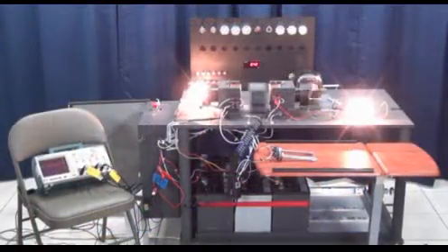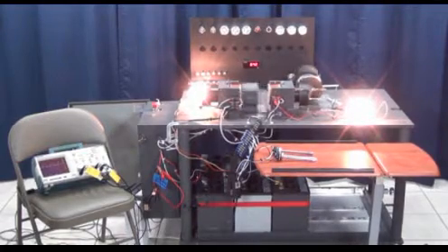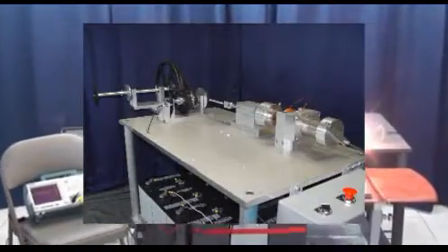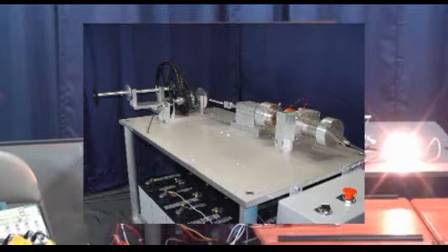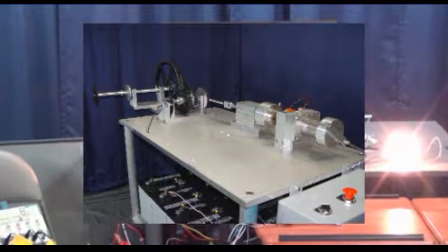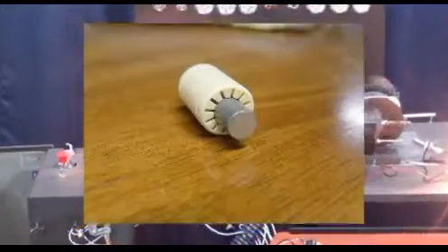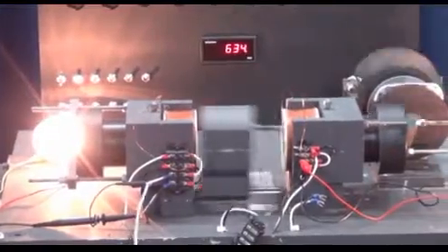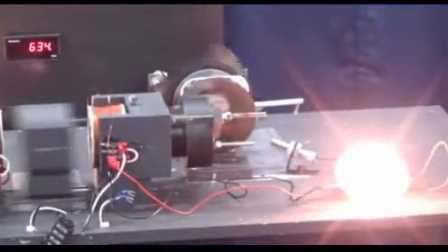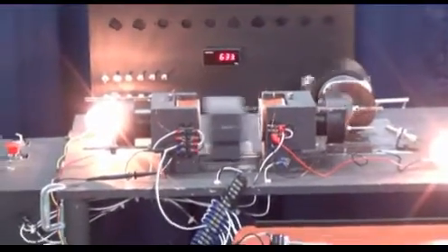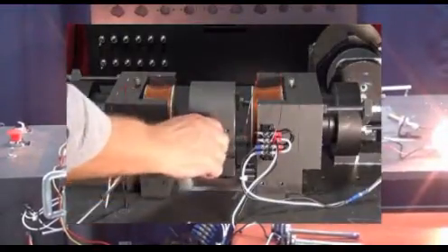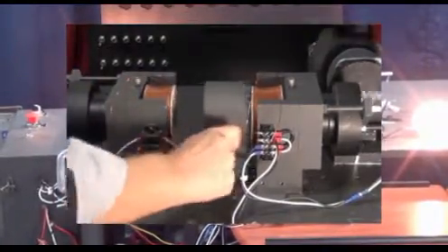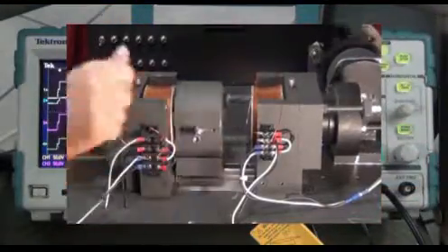One more problem. Magnetic force is not on centerline with the piston bearing. Note the single cylinder model and how it is centerline. But again, the magnetic friction on the bearings. Solve this with IGUS bearings. Putting centerline of all magnets on centerline of the shaft will increase performance also. The way the magnets are positioned and matched in power, magnetic neutralization is almost already present. It doesn't take much power at all to operate this device.